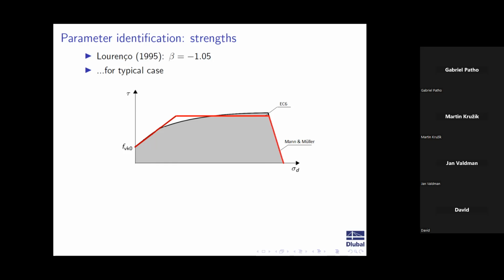What we assume here, we can compute sigma 1 and sigma 2, where these lines cross each other, and we compute the mid value. And this is a middle shear strength, a little bit modified with a factor 1.1, so we do not take it on the line.